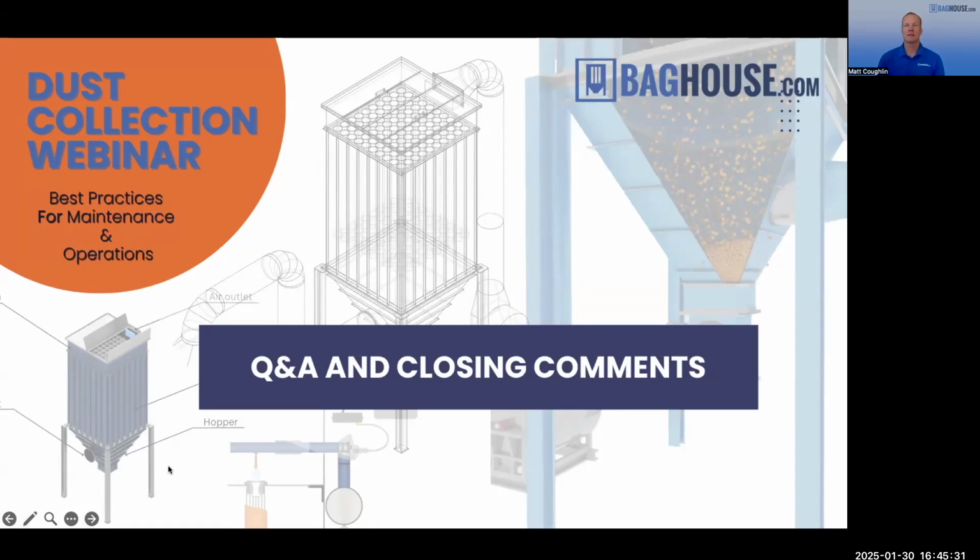The downtime or the wait time will kind of depend on how heavily loaded your baghouse is. It's not uncommon, we'll go do an inspection and we'll hear them pulsing every 10 seconds, which is too fast for almost every application. It's maybe just a default setting on the Dwyer timers or whatever it is. Like I said before, I think clean on demand is best, so you're not activating your system until it's needed.